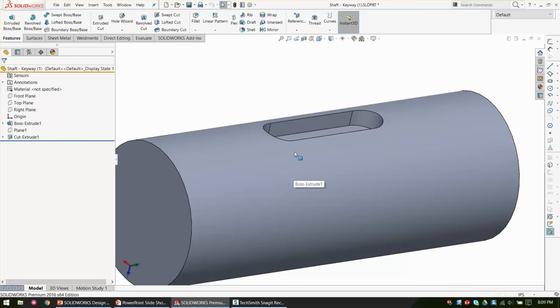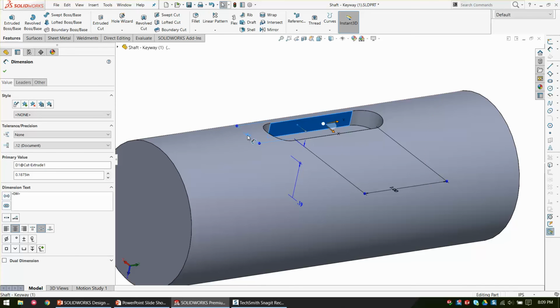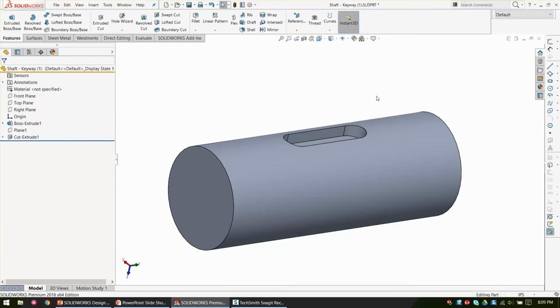It's really hard to argue with that. We've got a 3/8 keyway, which is half the depth down, so we have 3/16 cut down, and our inch wide, right? Who's done this? Who's seen this? This is just how you do keyways, right? Yes? Yes. All right, perfect. And again, we're not talking geometry. Geometry, every example we look at will be identical, so we're not talking geometry, just design intent.